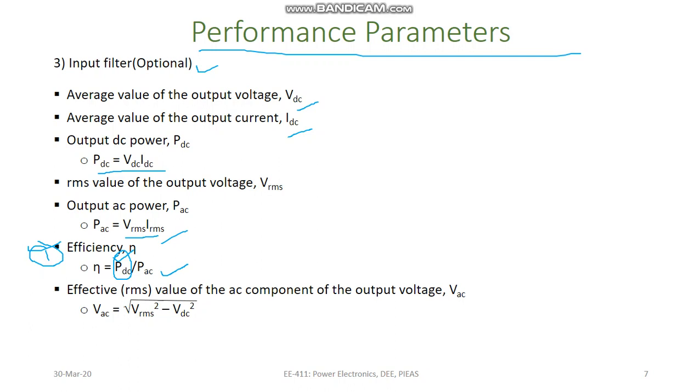So in an ideal case scenario, this efficiency can be 100%, which means that the AC power supplied has been completely converted into DC without any ripples in the output waveform and any loss in our diode or any other part of the circuit.